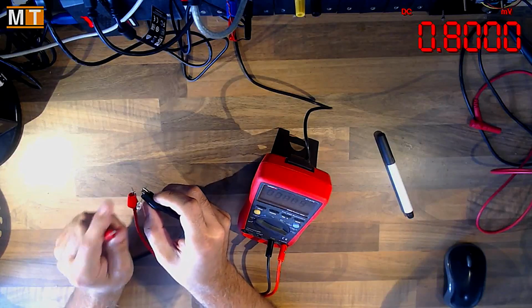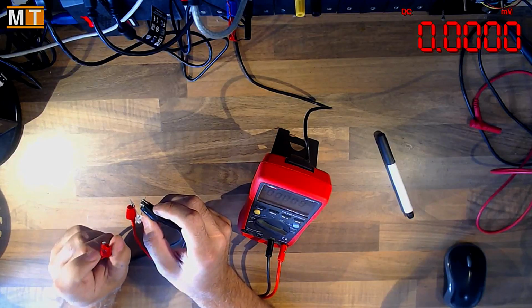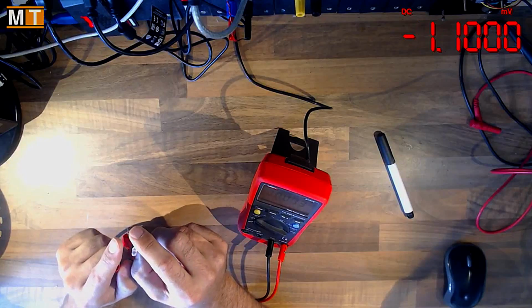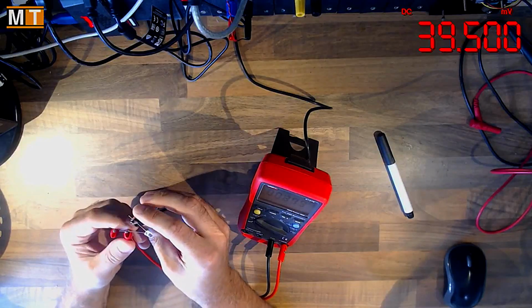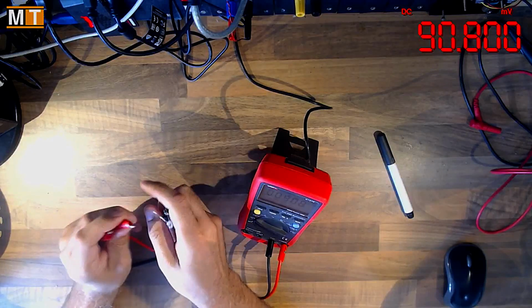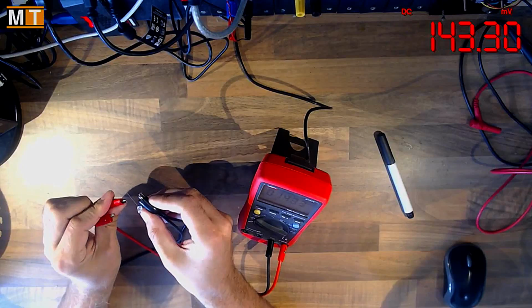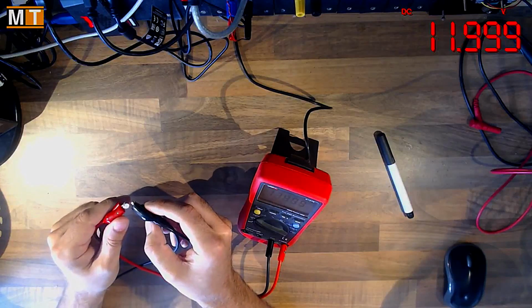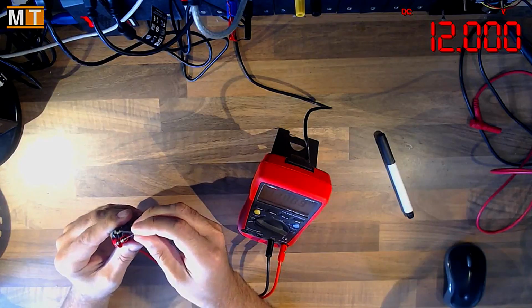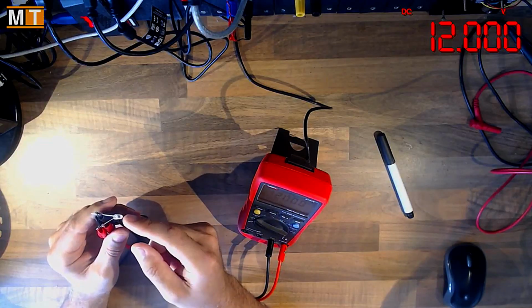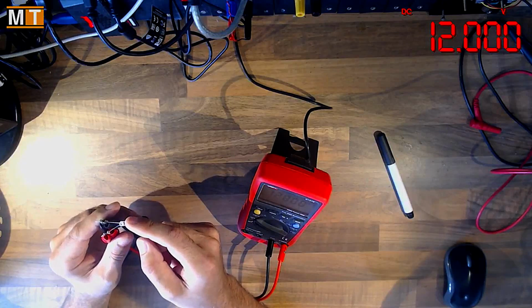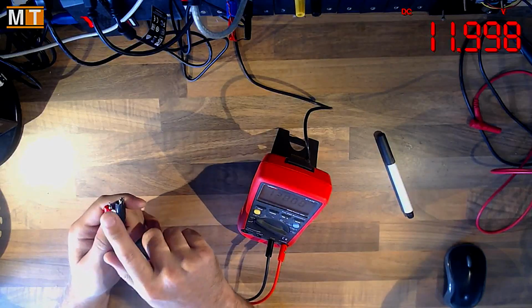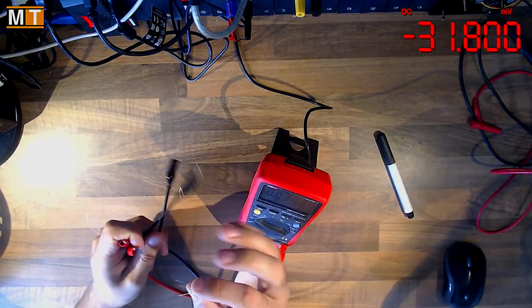Why did that blow? That blew because the power supply couldn't respond fast enough. So it got the full 12 volts across the LED with a full current load before the power supply could clamp down to the 2 volts that the LED needed. And you can see as well that the voltage across the LED is now 12 volts. So this LED, even though it's limited to 20 milliamps, has blown open circuit. There's no current conducting through because we've got the full 12 volts directly across the LED. One dead LED. Casualty number 1.